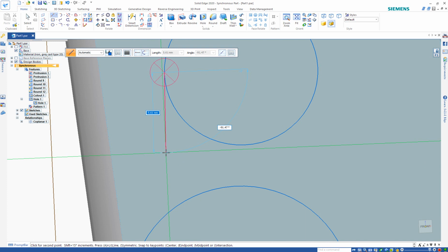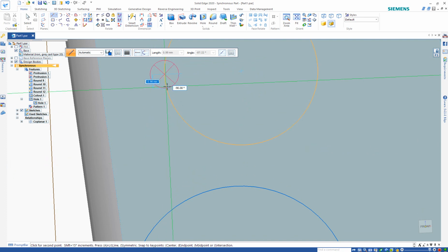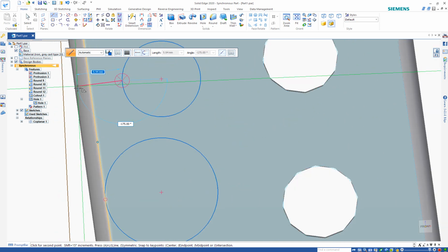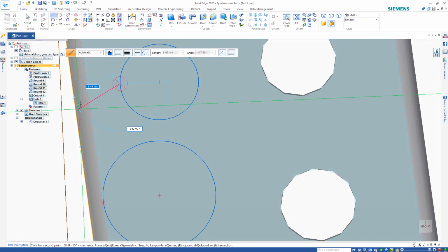No matter how you move your cursor, if it's outside of these 2 zones, it will always be tangent to the curve. And with these 2 zones, you're telling the software you want it to be either perpendicular to the curve or at any other random direction, okay?